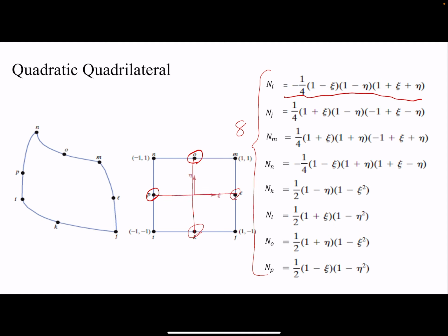If we use one quadratic quadrilateral element, at the end we are going to have a smaller stiffness matrix, because with 4 linear quadrilateral elements, we are going to have a node here as well, and each node is introducing degrees of freedom, and those degrees of freedom will appear in our stiffness matrix as well. So we are going to have a higher order of our stiffness matrix. That's the main difference. The other difference is that 2 linear elements are not necessarily equal to a quadratic element.